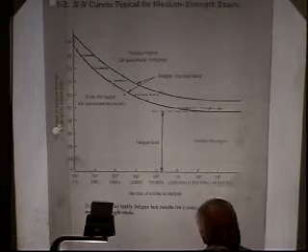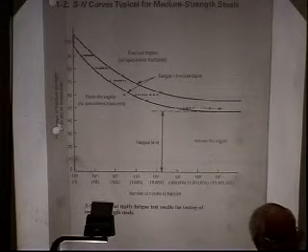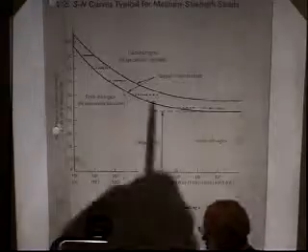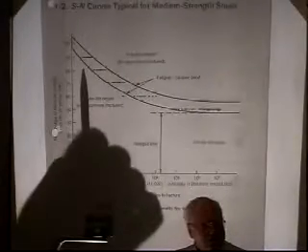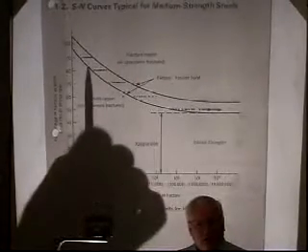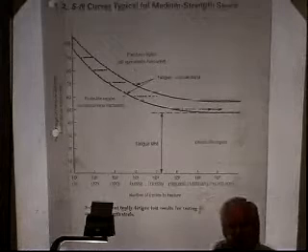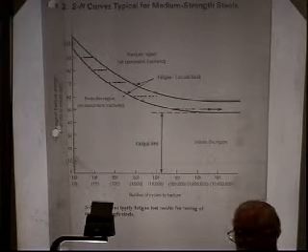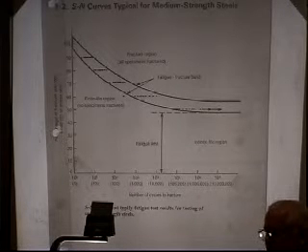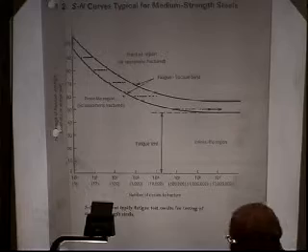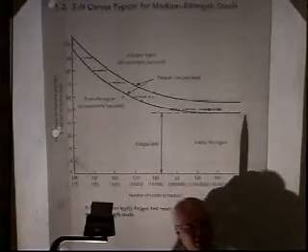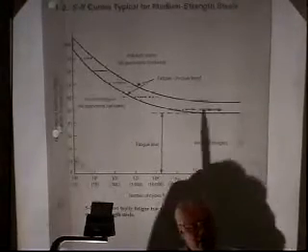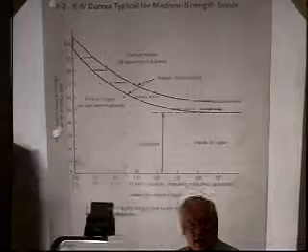So if you take the paper clip and you bend it and it stays bent, you're going to be in what's called low cycle fatigue down here, below about 100,000. If you go above, you can take it like a diving board and stress it, but it springs right back to its original position. So that's elastic fatigue over here. High cycle elastic fatigue, lower stress; low cycle plastic fatigue.